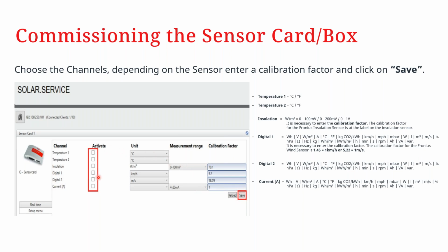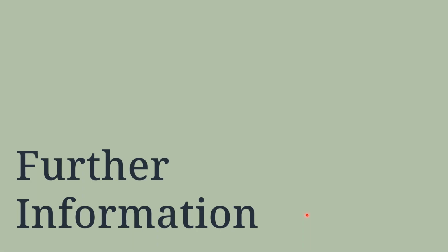So once all your configuration has been done, please ensure that you select save. Once you click on save, your settings will be saved, and then you can now monitor seamlessly using the Fronius Solar.Service.